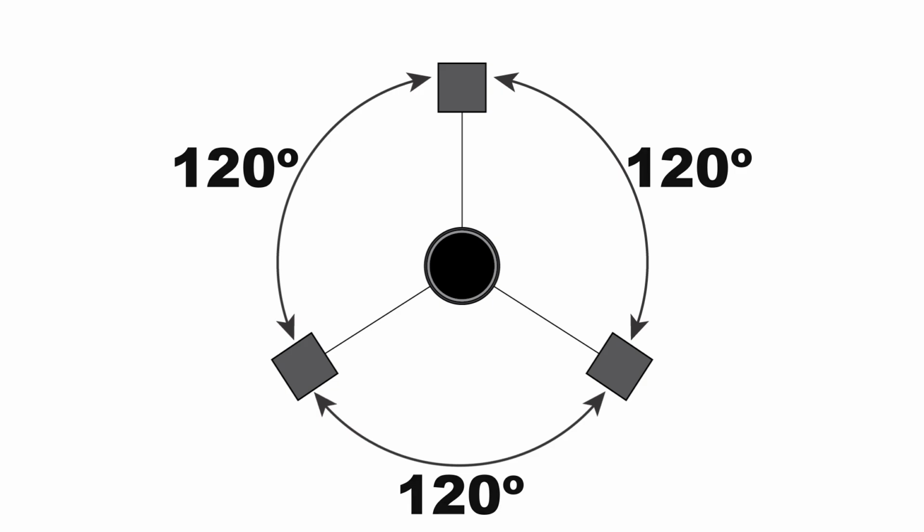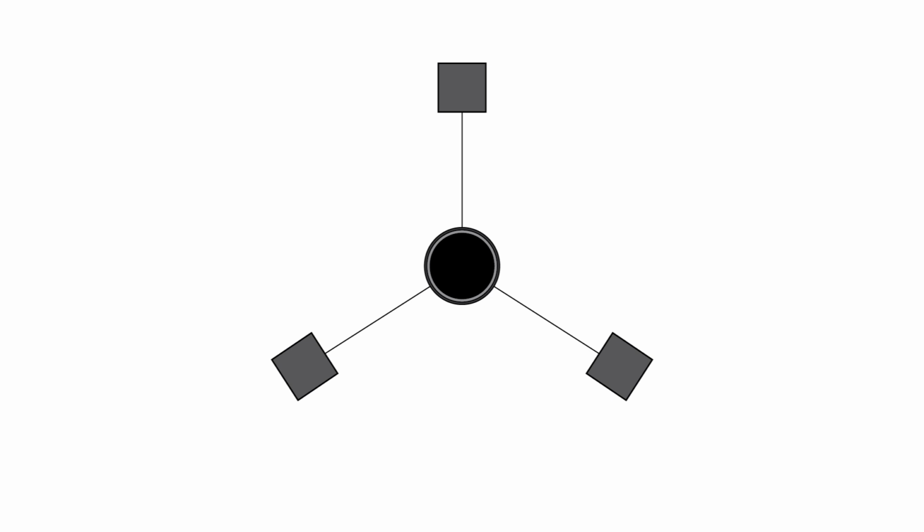Since 3 guy wires per set is the most common, we will use that for our discussion. When the deadmen are symmetrical, we can reduce the analysis to consider 3 different load directions: the 0-degree load, which bisects 2 of the cables, the 30-degree load, which acts along one of the guy wires, and 60 degrees, which is perpendicular to one of the guy wires.